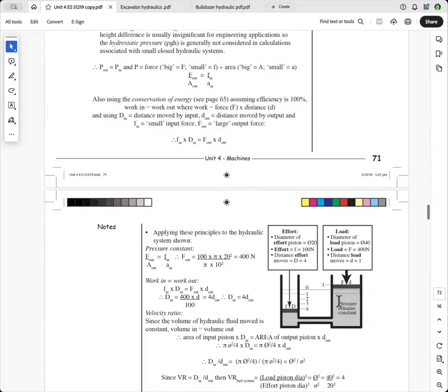This is a similar hydraulic system. I haven't shown a valve here. You'll have a one-way valve there. And if any of you have used one of those little bottle jacks, you know that you screw a screw to keep the valve open, or then you unscrew it and it will close it or open it, depending on the jack.